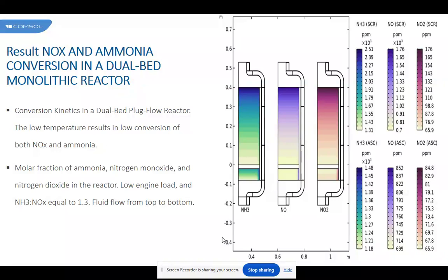In view of the literature extant on the subject of the effect of fluid distribution and cell density on the light-off performance, and recent commercial developments, this simulation presents a computational study of the effects of using dual cell density structures in monolith catalytic converters. The effects of such structures on the velocity and temperature distributions and subsequently on the chemical conversion is demonstrated for a variety of dual cell configurations.